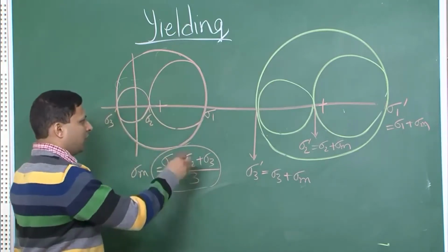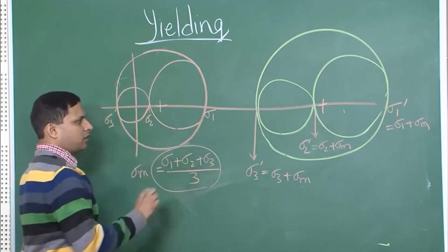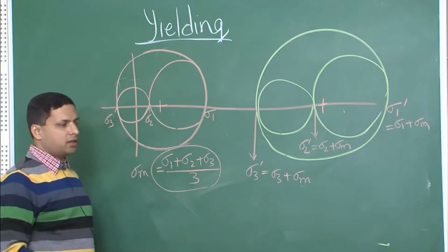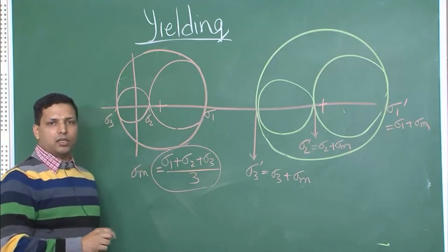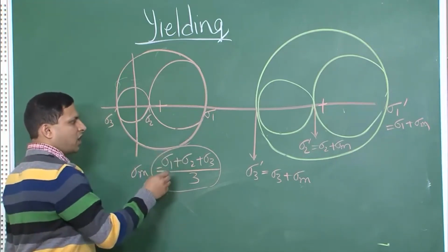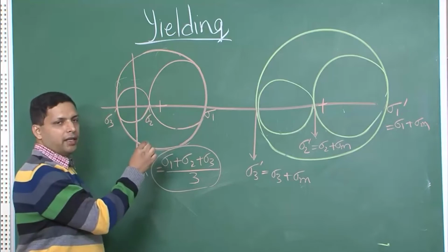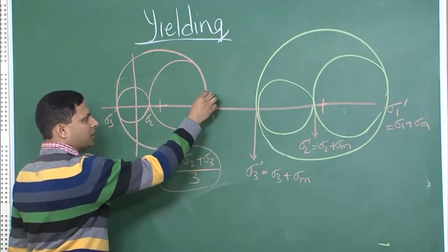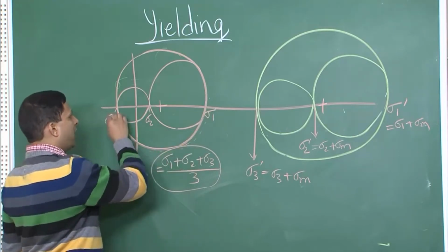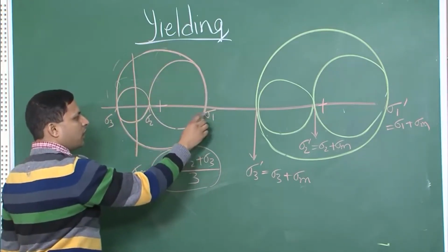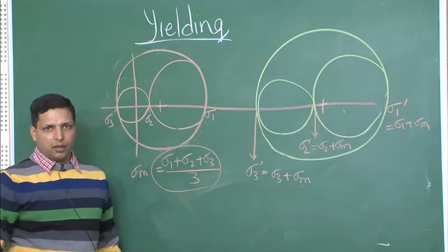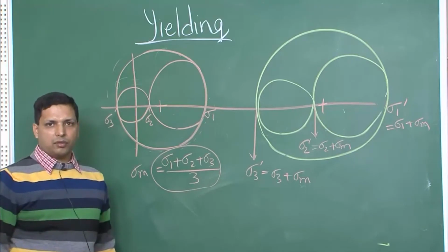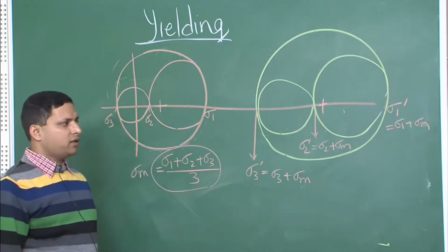And therefore, if you are changing something which causes a change in the size of the diameter of the circle, that is the only thing that can actually change the state of yielding. So, let us say we start with a very small circle, where yielding is not taking place, and keep increasing it. There may be some critical size at which yielding takes place. As soon as the circle size reaches this value, the material starts to deform plastically, and anything beyond that the material has yielded.